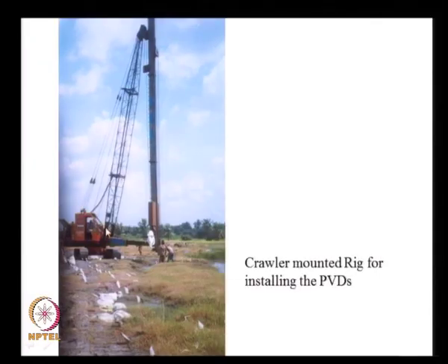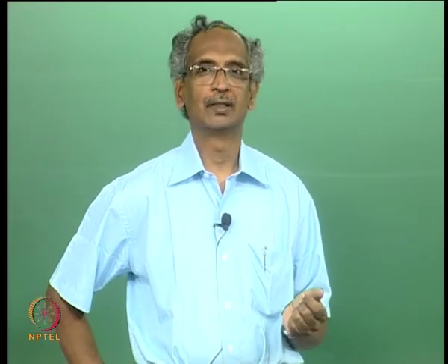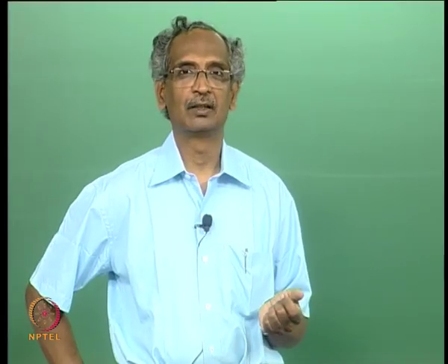And yeah, here we see the entire view with the entire boom, and the PVD is installed by just simply pushing. And in some cases, if we are not able to push, we also use the water jet to assist in the installation. And typically to install a PVD of about 10 to 15 meters, it takes hardly 3 to 4 minutes.